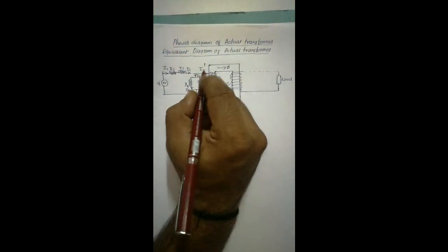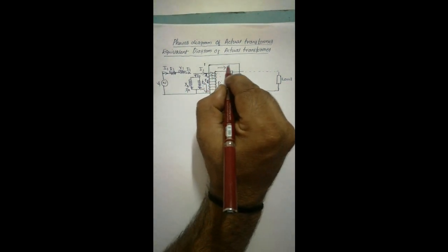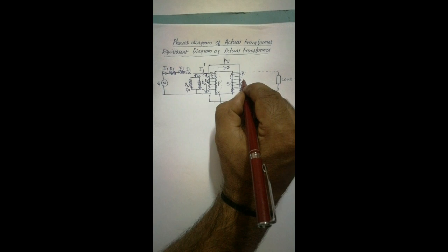After removing all these things, we will get a voltage E2 here. Then this flux passes to the secondary side of the transformer. It is a rate of change in nature, in a sinusoidal way. This flux will link to the secondary winding, and an EMF will be generated in this winding, whose voltage depends on the number of turns of the coil. So a voltage E2 will be generated here.